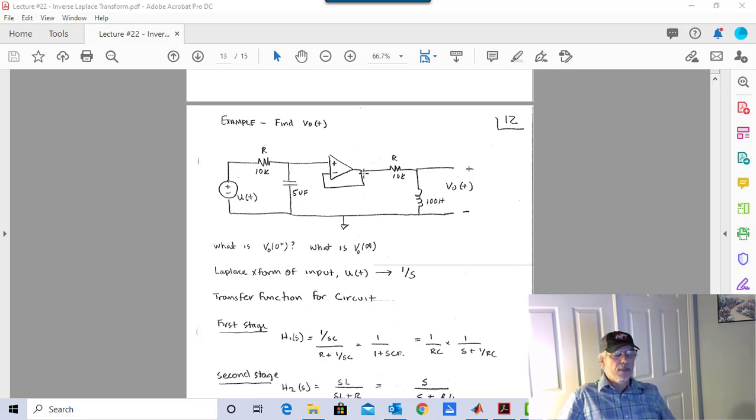here. And then I say, oh, darn, at t equals infinity, that's steady state, and there's going to be no voltage across that inductor, so I just wasted my time with everything I did over here. But I got a lot smarter. So V out of infinity is 0. And now that we look at it correctly, we say the reason for that is because there's no steady state voltage across this inductor. I don't care what's going on back here.